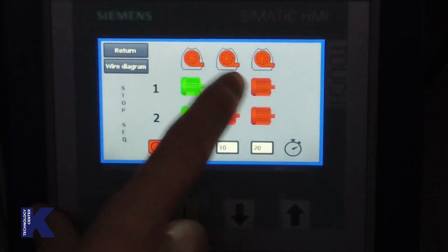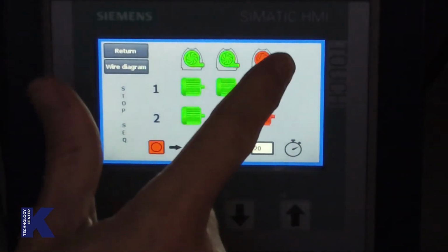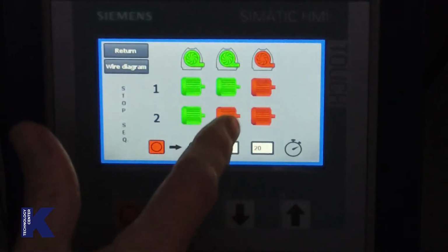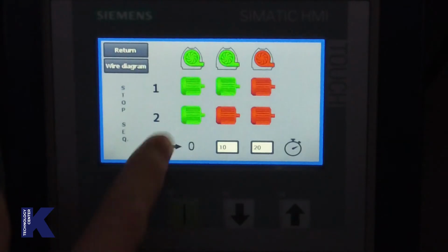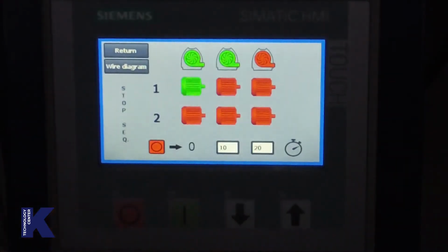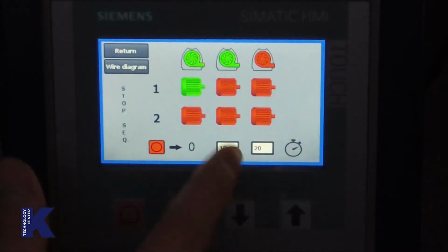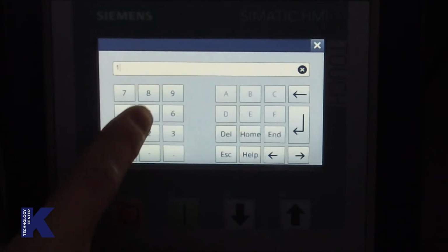But we would like that you can see here by selecting the blower at the end, then suddenly the 2 first steps would be unselected and then the blower would still run. So now we have a sequence that when we're pushing the stop, the second motor stops, 10 seconds later the first motor stops, and 10 seconds further also the blower is stopped.